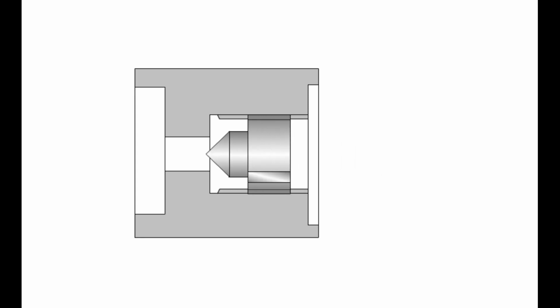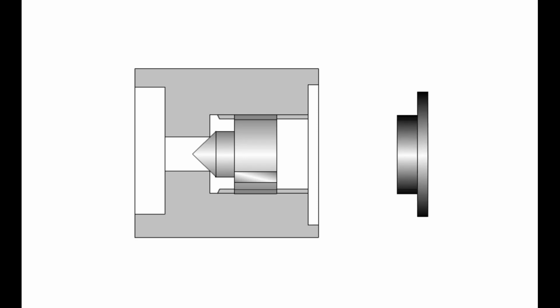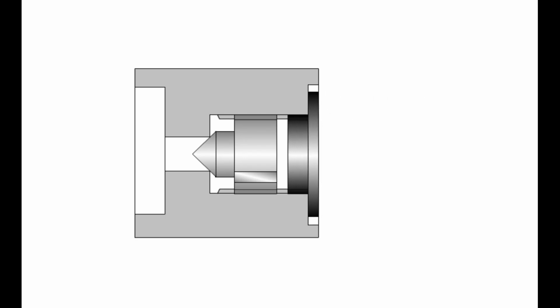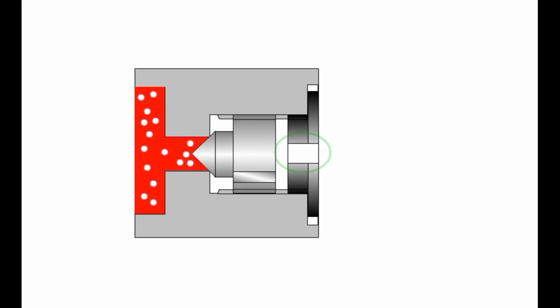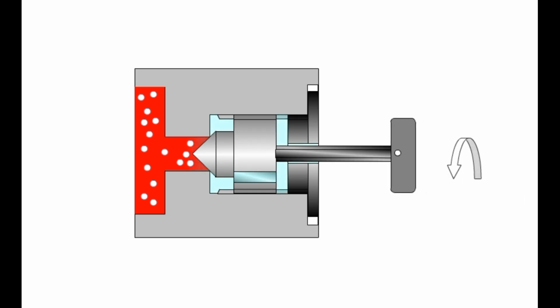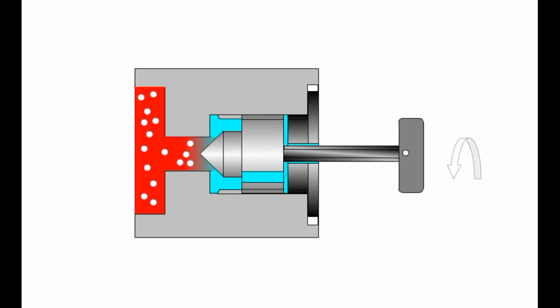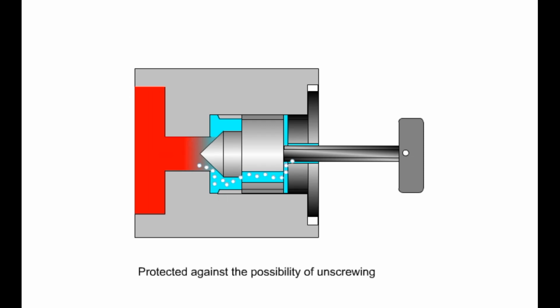An air bleed valve is screwed into the respective drilled hole in the cylinder. The drilled hole is sealed with a protective cover. A protective cover is provided with a drill hole to allow the air bleed valve to be opened with a hexagon wrench without removing the protective cover. The protective cover ensures that the air bleed screw cannot be unscrewed too far and fall out.